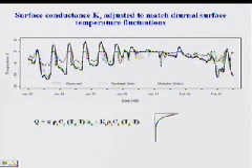Then the surface temperature, at least during this time step, was flat during the day when the snow's at 0 degrees C. We adjusted the surface conductance so that we matched those depressions, which suggests that we are getting the right balance of conduction with this exponential decrease of the penetration depth of surface fluctuations. So that's how we came up with surface conductance.